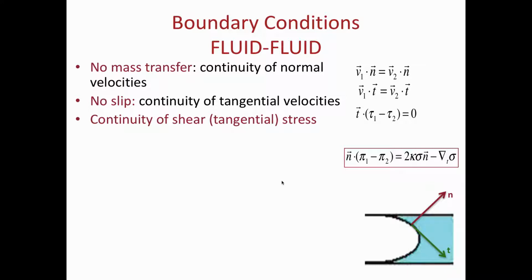Okay? Now, what's key is, if these derivatives of velocity are not very large, and for laminar flow they're not, then what's going to dominate the situation is the difference in these mu's. And the viscosity of air is very small compared to the viscosity of the fluid, so the viscosity of air is 0, which is how we said the shear stress at the air-liquid boundary should be 0.